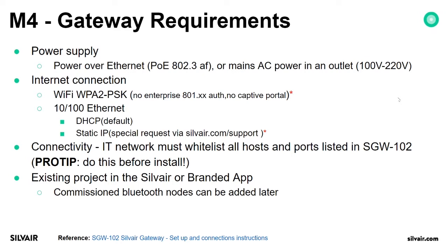Gateway requirements. First of all, power supply: Power over Ethernet, PoE 802.3af, or main AC power, 100 to 220 volt.